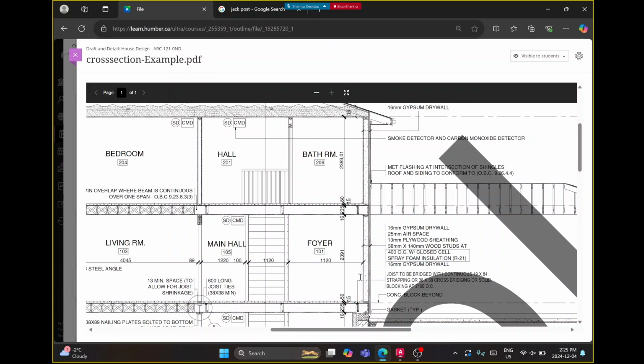Here you can see it's got 2x4s in it. So as soon as you see a 2x4, you know it's 89 millimeters wide. So this wall is 89, and it's in line. This is where the stair cuts to the floor here, and it's opposite the 89 millimeters.